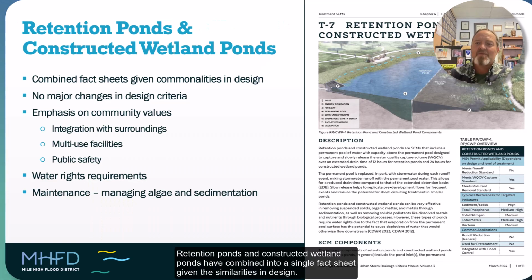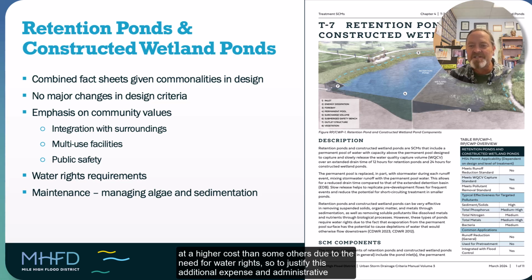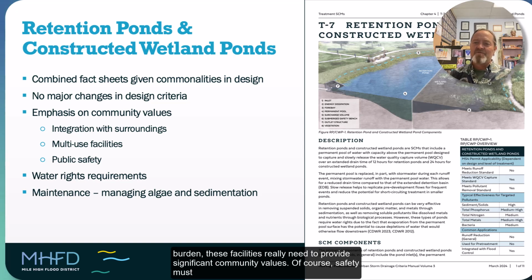Retention ponds and constructed wetland ponds have been combined into a single fact sheet given the similarities in design. There have not been major changes in the design criteria for these SCMs, but the updated fact sheet provides new graphics and expanded guidance on integration with the surrounding site and community values. These SCMs come at a higher cost than some others due to the need for water rights. So to justify this additional expense and administrative burden, these facilities really need to provide significant community values.